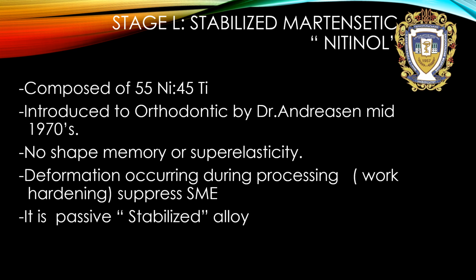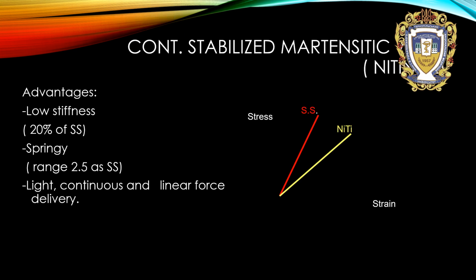Stabilized martensitic nitinol, composed of 55 nickel and 45 titanium, was introduced to orthodontics by Dr. Andreasen in the mid-1970s. No shape memory or superelasticity. Deformation occurring during processing is suppressed. It is a passive stabilized alloy. Diagram. Advantages: low stiffness, springy, and high continuous and linear force delivery.